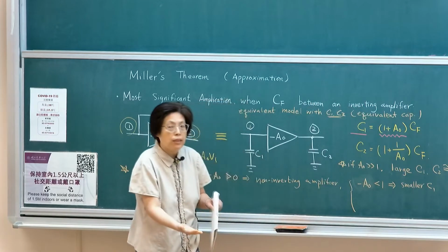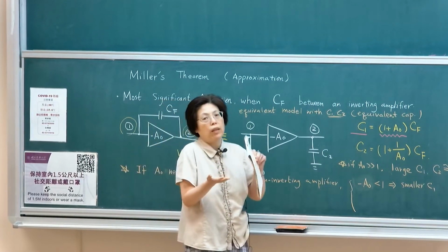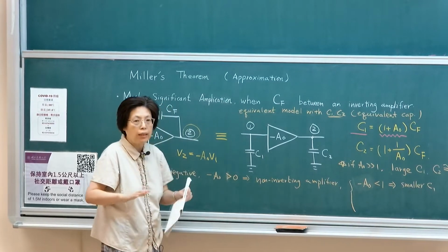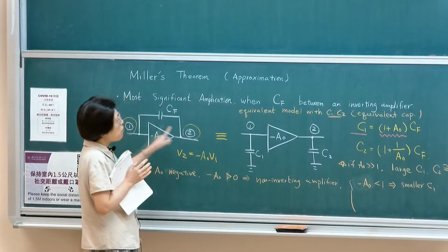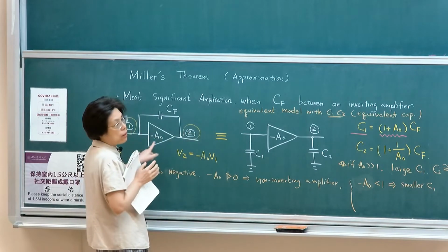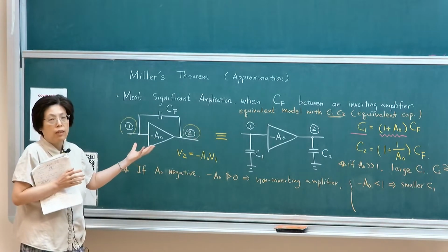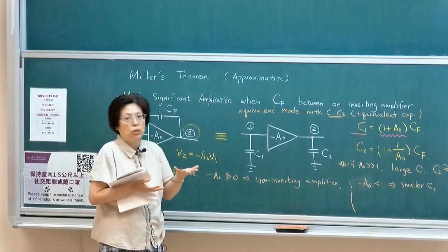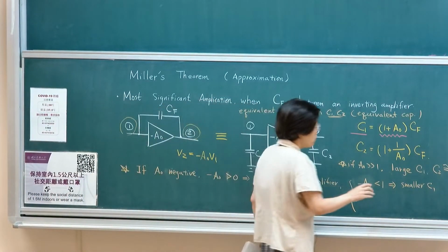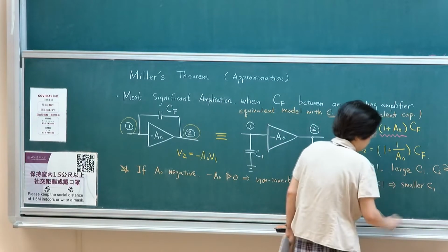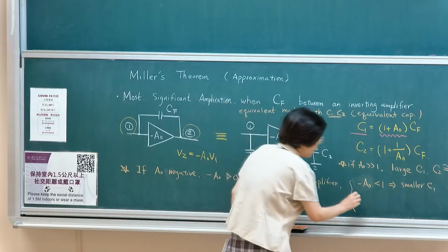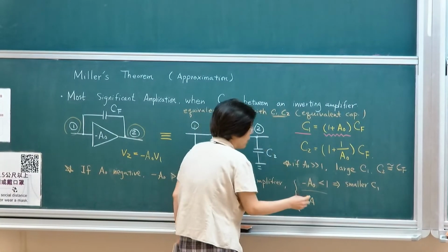So this is when the opposite side is lifting as you're moving upwards. So this is like if you have a source follower. What happens is that this will follow this. If this one is, let's say, a gain of 0.8, then you don't need to actually feed that much current. So you would then see effectively much smaller C1.